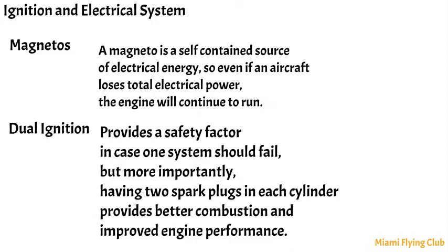The ignition system in an aircraft engine is entirely separate from the aircraft electrical system. The engine can operate normally with the electrical system turned off. The only time the engine needs the electrical system is to turn the starter.